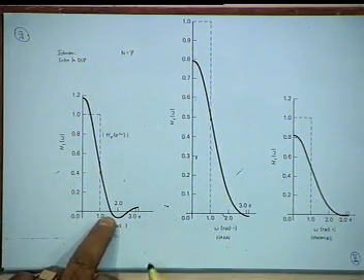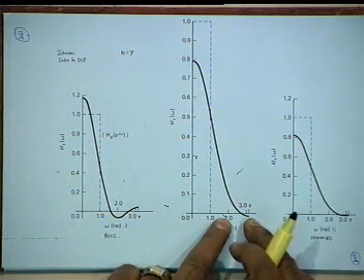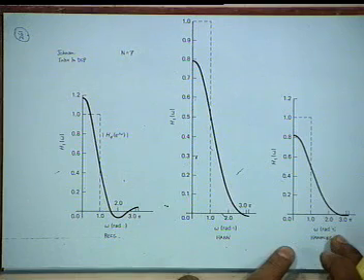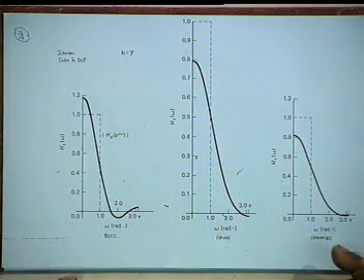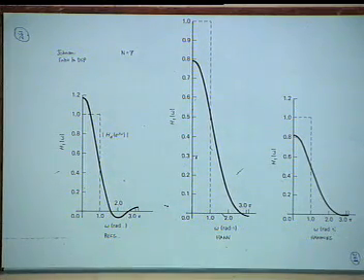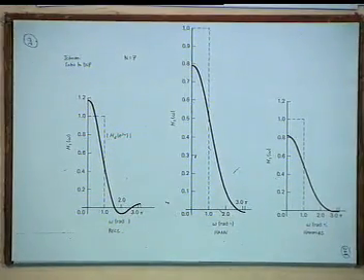You see, zero crossing is between 1 and 2 in the rectangular window, but it is between 2 and 3, closer to 3 than 2 in the Hann as well as Hamming, which is a reflection of the widening of the main lobe. Agreed? And therefore, what is the effect on the low pass filtering? The cutoff becomes slower. Rectangular window gives you a sharper cutoff than either of these. Okay? And this side lobe height is reduced considerably. You see here, Hamming, for example, it is hardly discernible.